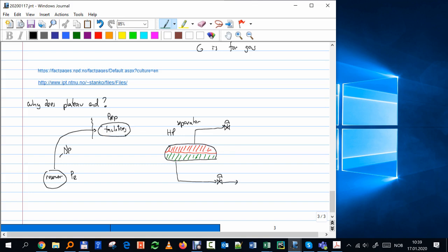First you have a level controller. Let's say in a very simplistic way it's a floater. You want to make sure that the level is at a particular height. If it goes too high, what might happen? You might start getting liquid into this line, which is not good. I have compressors and all kinds of things that depend on the phase being primarily gas. So this controller is controlling this valve and making sure that the level is within a range. How do I call these ranges in the separator? Low level and high level. So you have low-low level, low level, high level, and high-high level, I think. You want to be within the band. If by any chance the level starts to get too high, then that valve will open.